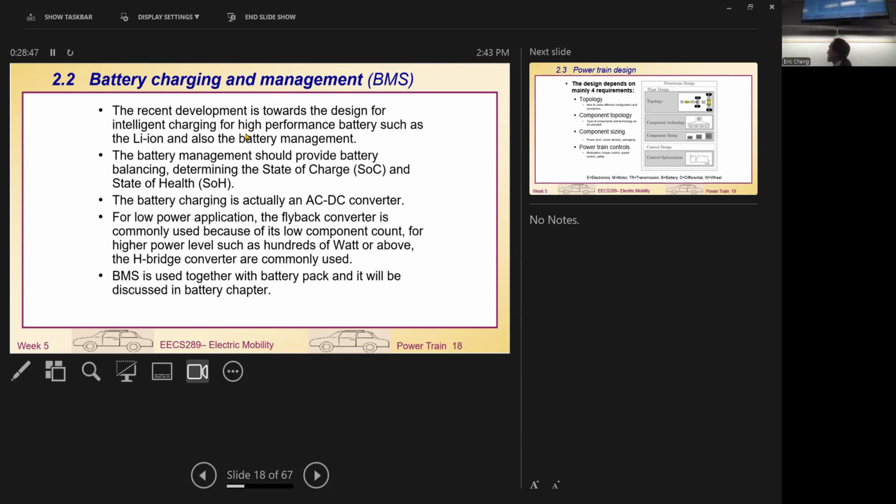The battery system itself has an internal BMS to check the current condition and the battery condition to do the job. So it doesn't care what kind of charger you're using, as long as it follows the charging standard. I think the next few lectures will mention the charging standards. We just work the battery along with some international standard, then it should be okay. Internally, the BMS, the battery management system, works with each battery cell properly. It controls its safety, its current, the state of charge, state of health, and temperature.